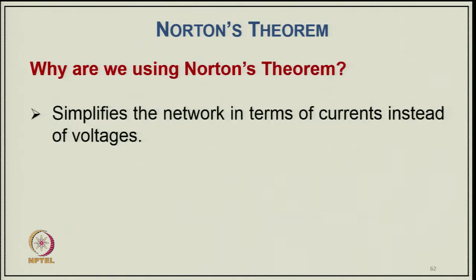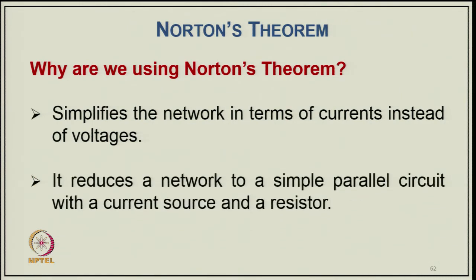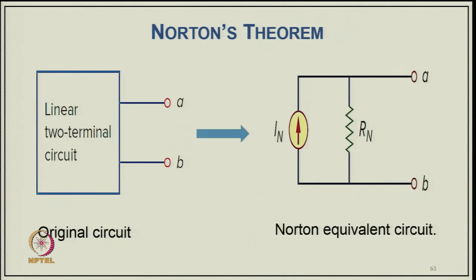So why are we using the Norton theorem? It simplifies the network in terms of current instead of voltage. It reduces the network to a simple parallel circuit with a current source and a resistor. And there is an analogy between the Norton theorem and the Thevenin theorem.